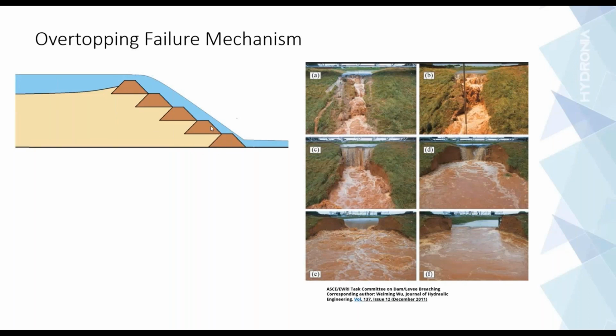So the problem with this is that even though maybe the first dam foundation was well conceived, the others are founded on previous deposits of the tailings. And that creates sometimes instability in the structural conditions of these dams. And also, they tend to be very susceptible to the overtopping failure due to the overwhelming capacity of the upstream dam itself.